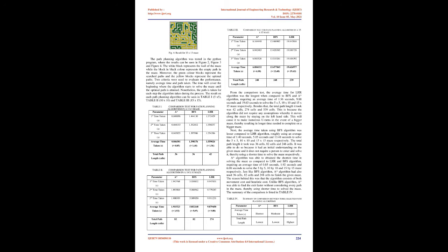The summation of both movement cost and heuristic cost will be evaluated as the fitness cost. It will be listed in the open list, while the node with the lowest overall cost will become the new current node 10. The equation of the fitness cost can be seen, where f(n) represents the fitness cost, g(n) represents the movement cost and h(n) represents the heuristic cost. The whole process is repeated until the desired ending location is reached.